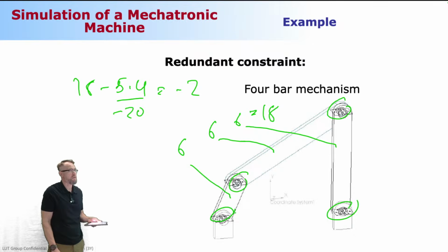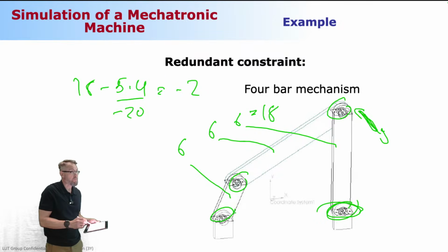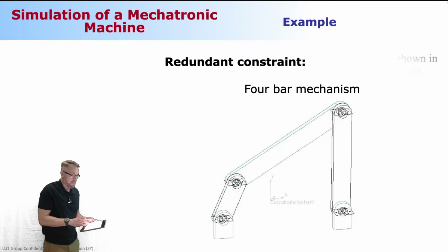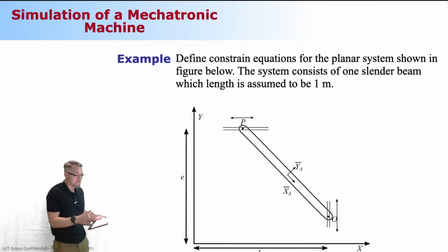So this is our constraint system, simply because the motion in this transverse direction is over constrained. You don't need this many. You just simply could release one of these revolute joints and put the primitive joint there instead. And then you end up with a positive number, as a modeling trick. All right, let's practice a little bit more.